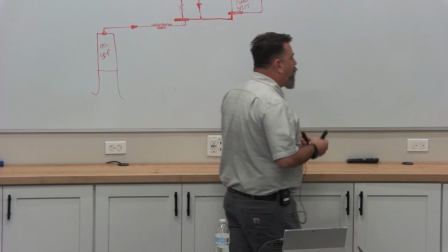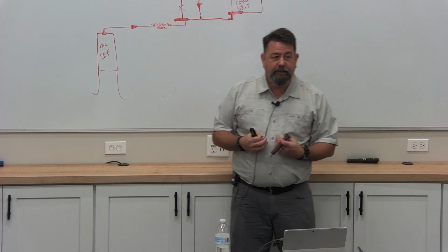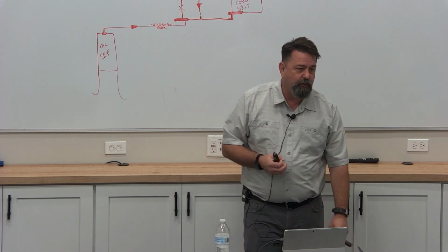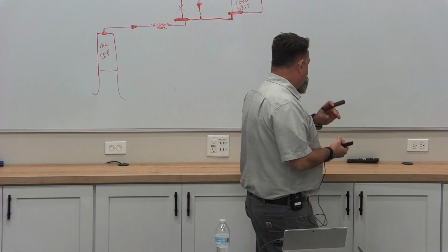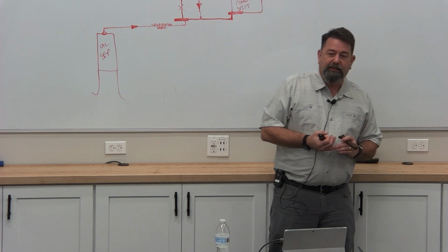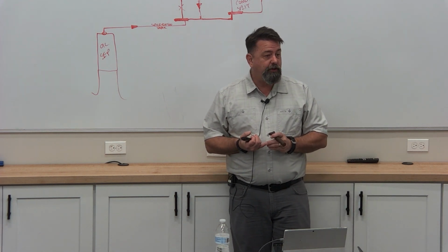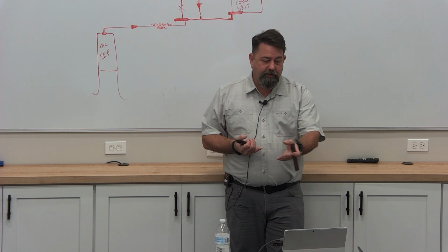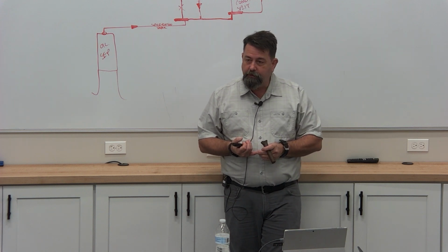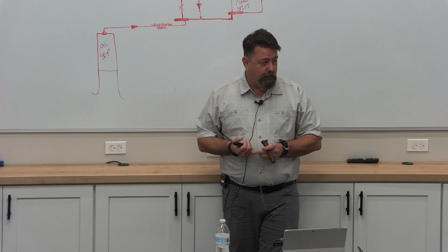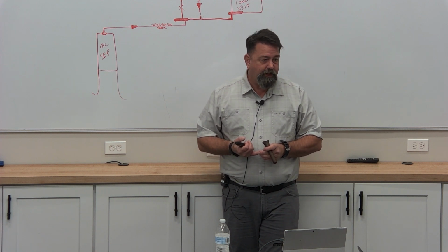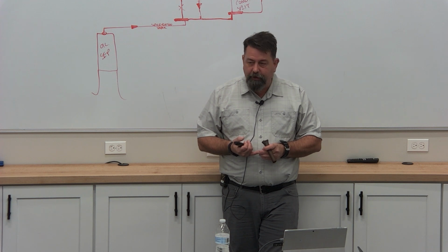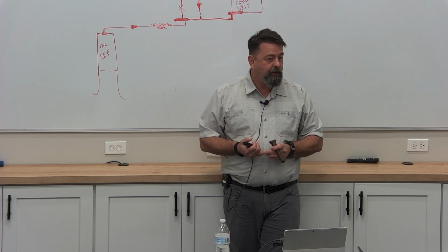So we're gonna use that 140 as technicians, as service techs, since I just told you you're not gonna match that. So what's the point? Well, we're gonna use that as the basis. We're gonna know that that's the most I should have, and that I'm gonna read less. So if I walk up to this case and I stick it on there and I'm reading 200, is that a clue? Yeah, it's a clue. Somebody's changed the blade and motor incorrectly. I'm moving more air than I should.